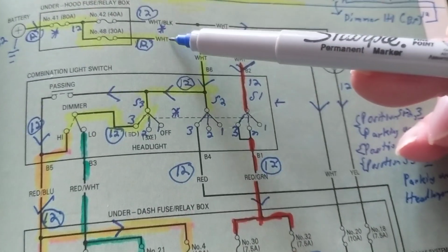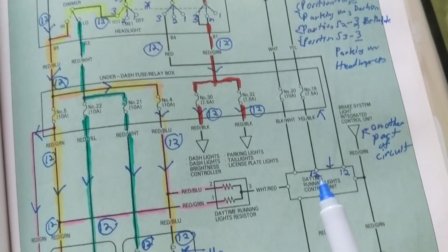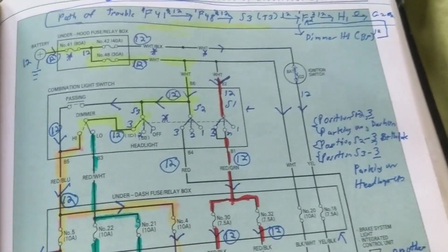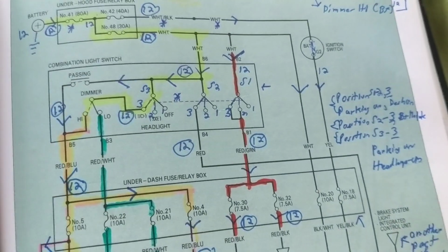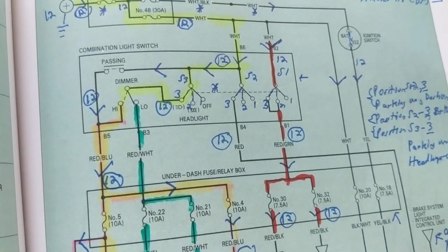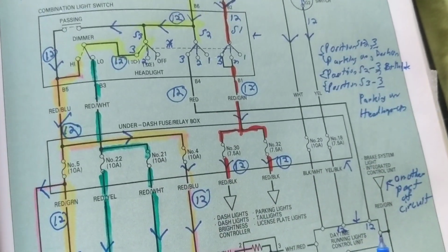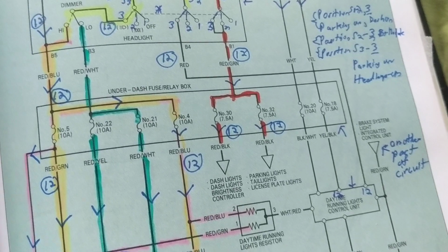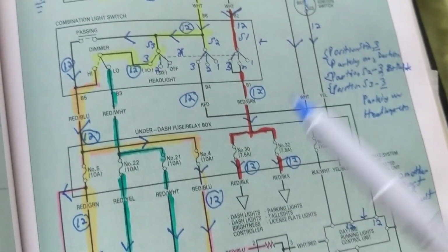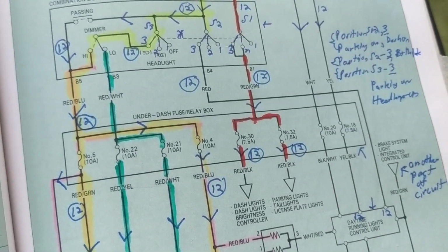schematics. Now, since we're dealing with lighting systems, we expect to see lights, bulbs, modules, switches, fuses. What we don't have here is relays. You will always see relays in fuel pumps, air conditioning, anything. There are relays, obviously, all over in GMs. This is just an educational schematic that I picked. There are relays all over. You have to know how relays work, which I did many videos on. Relay, one side goes to B+, the other one goes to ground. The computer can give that relay a ground, usually.